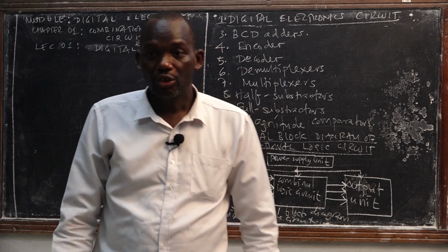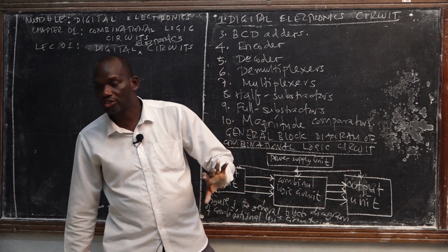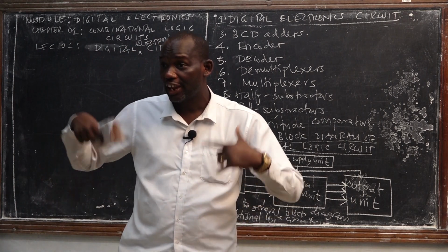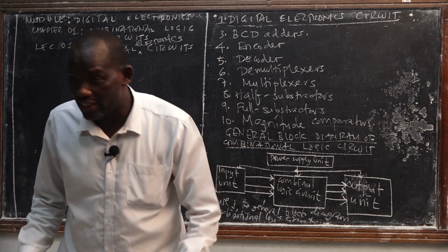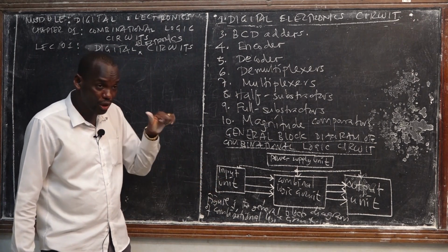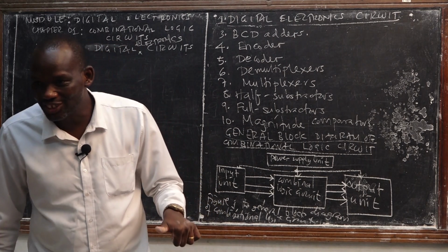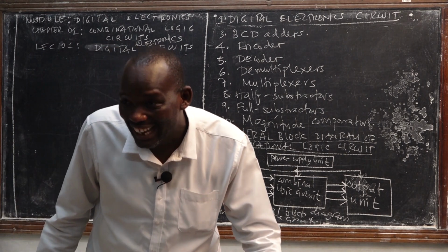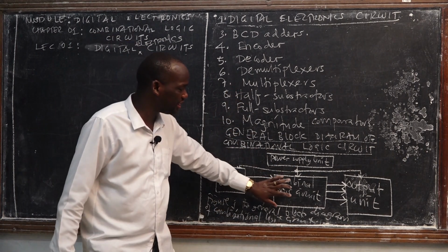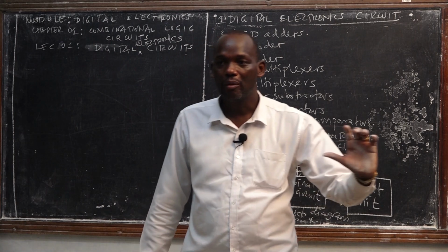Are we together? So electric motors either rotate clockwise or anti-clockwise. And remember that those are three-phase electric motors. So just hit a single button, a single click, because if you don't click, that is logic state high. If you click, logic state low. Right? Then the PLC receives the signal and sends the information to the AC motor.